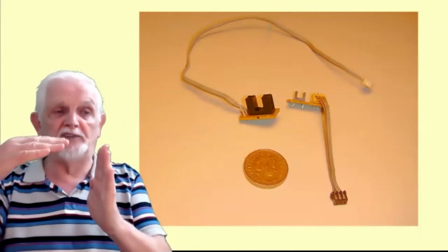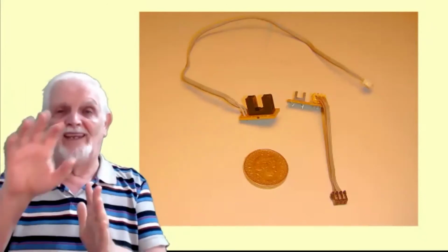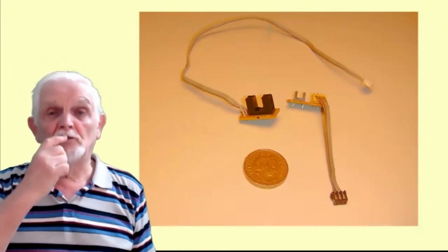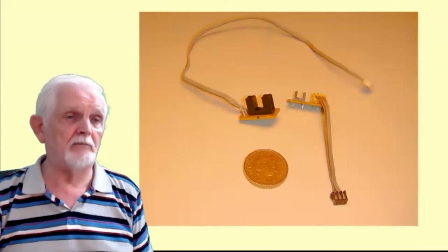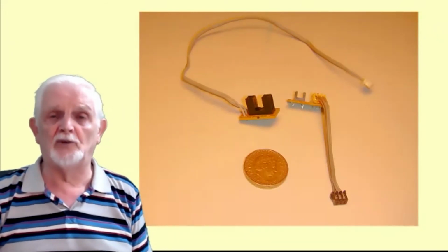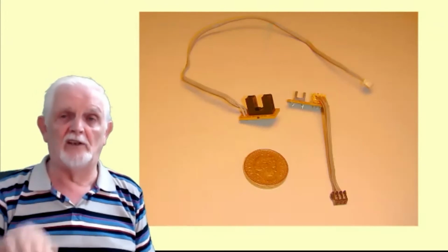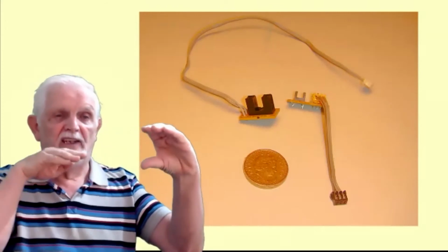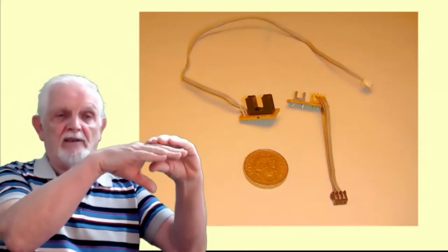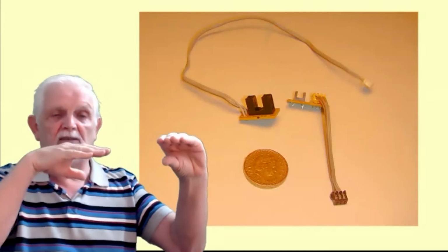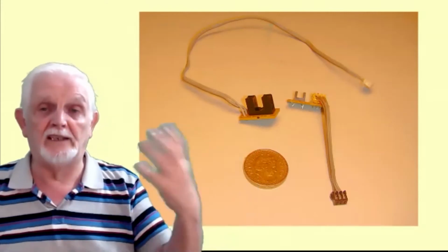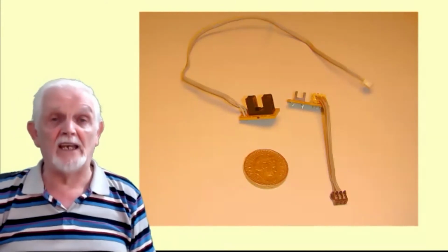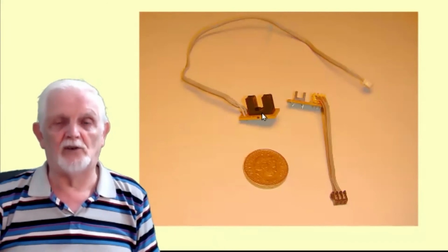And if you use 2 of these at right angles, you can go to any position in the plane and get an output stream. They're also used still for CDs and DVDs and so on to detect whether the tray is in or out. So you have the detector, the beam going across, and then the caddy can come in and block the light, or the caddy can come out and let the light shine through, and you can detect whether a particular mechanical piece is in or out of that plane.